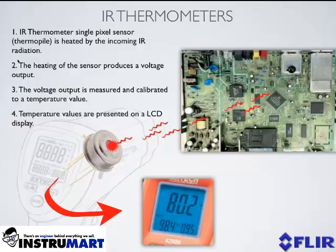They're all one and the same. The IR thermometer has within it a single detector element that senses infrared radiation. This detector is typically a thermopile. A thermopile is an electronic device that converts thermal energy or thermal radiation into electrical energy. Thermopiles do not respond to absolute temperature, but they generate output voltages proportional to a local temperature difference. Now, this changing output voltage from the thermopile is measured and calibrated to a corresponding temperature value, and the resulting temperature value is then reported on an LCD display.